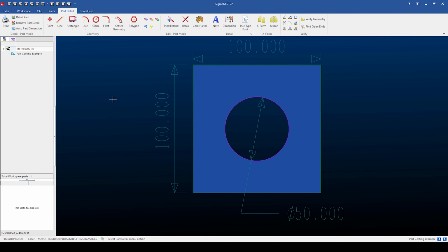Knowing the area, material thickness and density, we can work out the expected mass. Area times thickness times density per kilo will give a rectangular mass of 0.785 kilos and a true shape mass of 0.6309 kilos.